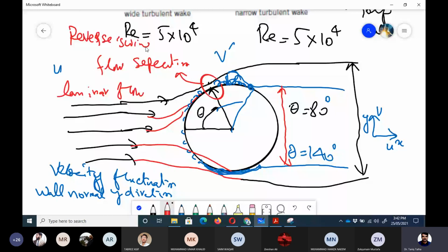So one side, which is the top surface in this case, we make shiny. The boundary layer would separate at theta equal to 80 degrees on the top surface, while we keep the other side rough, as it is. When the ball is delivered, there would be a vacuum on the top surface because the boundary layer has separated, but the flow would remain attached here.